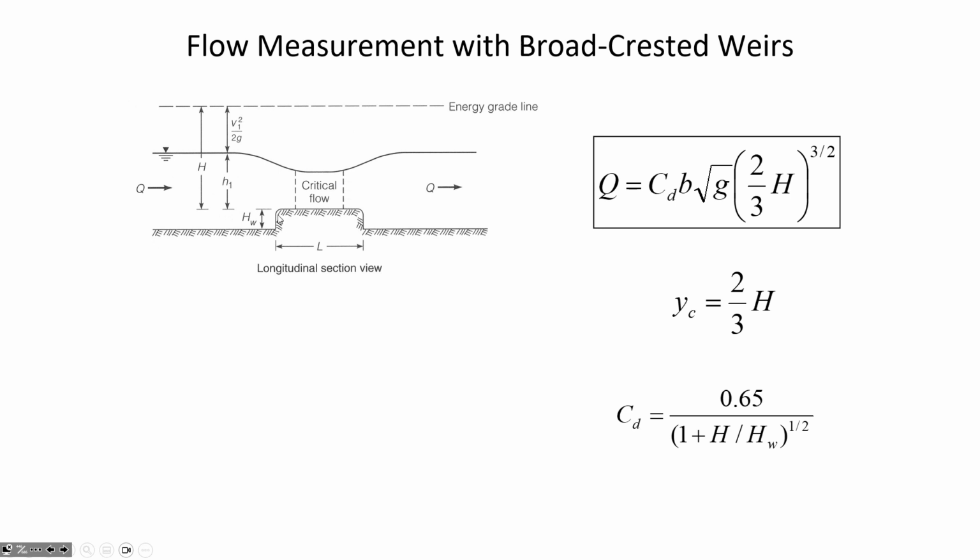If you're confident that the step is high enough to force the critical flow, then that allows you to determine the flow rate through the channel by measuring the depth of the flow, and then remember the little shortcut that the specific energy when the flow conditions are critical is 3/2 times the critical depth.